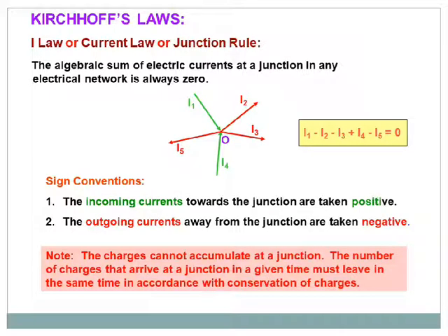So you can rearrange this equation and then write this as I1 plus I4, both are having plus sign. I1 plus I4 is equal to I2 plus I3 plus I5. By moving I2, I3 and I5 to the other side, that will change the sign from negative to positive, because we are changing the side of all this current. So that will balance the equation.